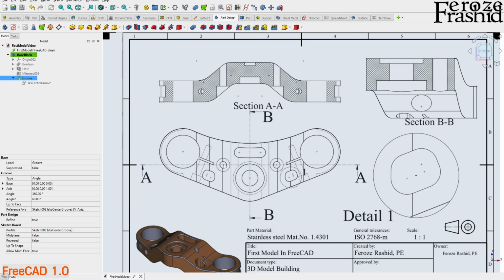So we already had those built in there. And now we can go counterbore them. Now, I wish I did not build those in here to begin with. I'll be honest. But since we already built it in there, we can apply a second feature to make it a counterbore hole. So what I will do, all right, let's bring our group back.